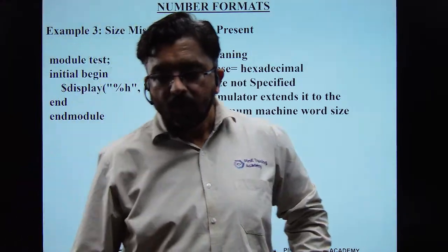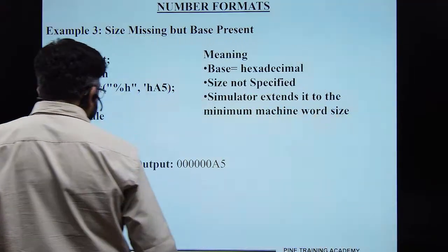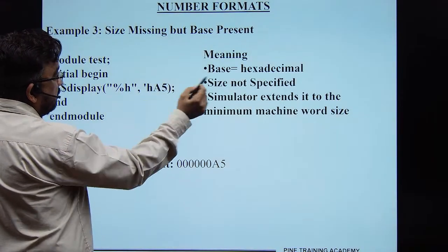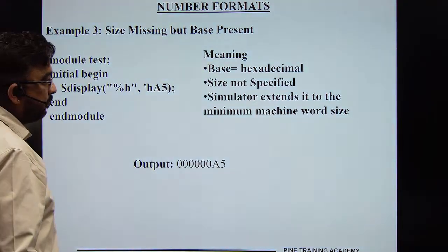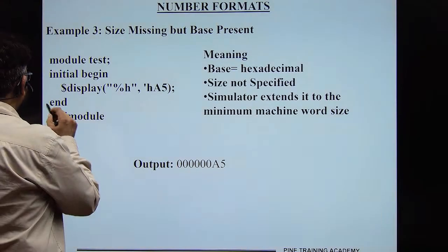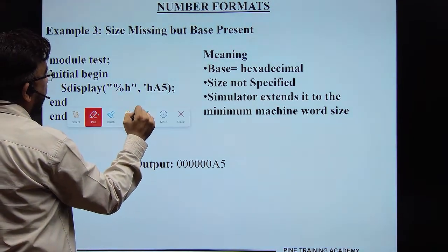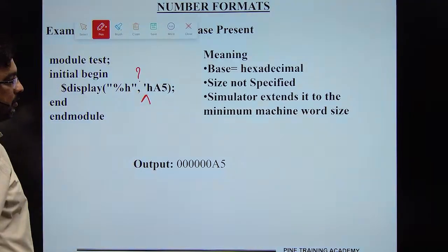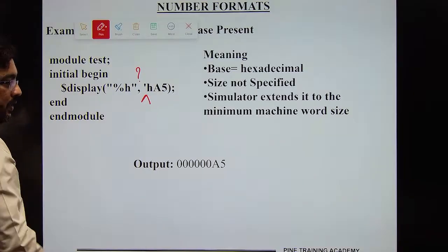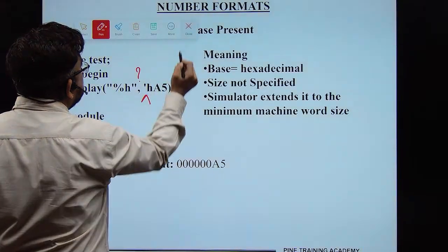Next, what happens if size is missing but base is present? If the base is hexadecimal and size is not specified, the simulator extends to the minimum machine word size. So if size is missing, the simulator extends to the minimum machine word size, and whatever you have defined, it will take. So this is one case.